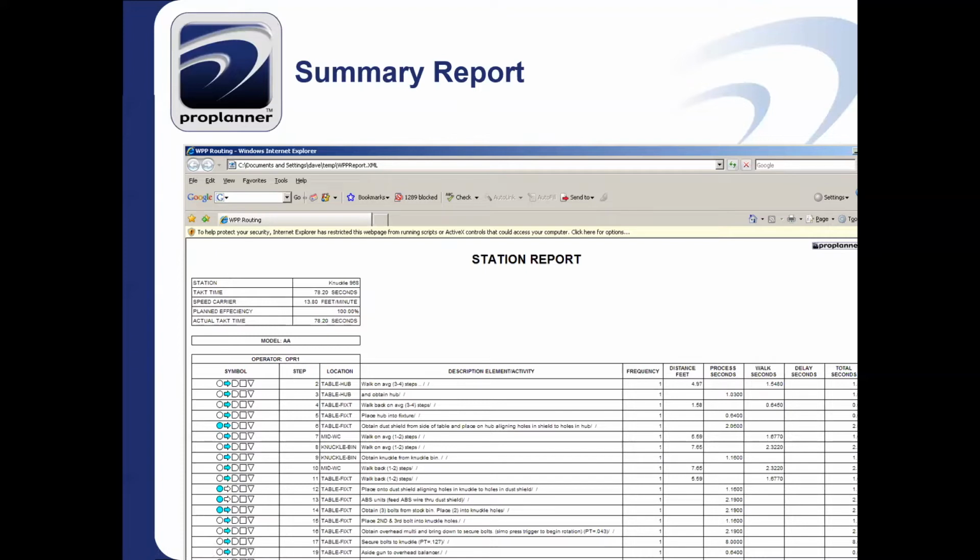So this allows me to take these different steps and identify the process symbology, where they're performed, and this is just a user-defined location. It's essentially going to be represented in the AutoCAD drawing as a text label on a certain layer of AutoCAD. So table-hub will be an AutoCAD text object in the drawing on a certain layer.